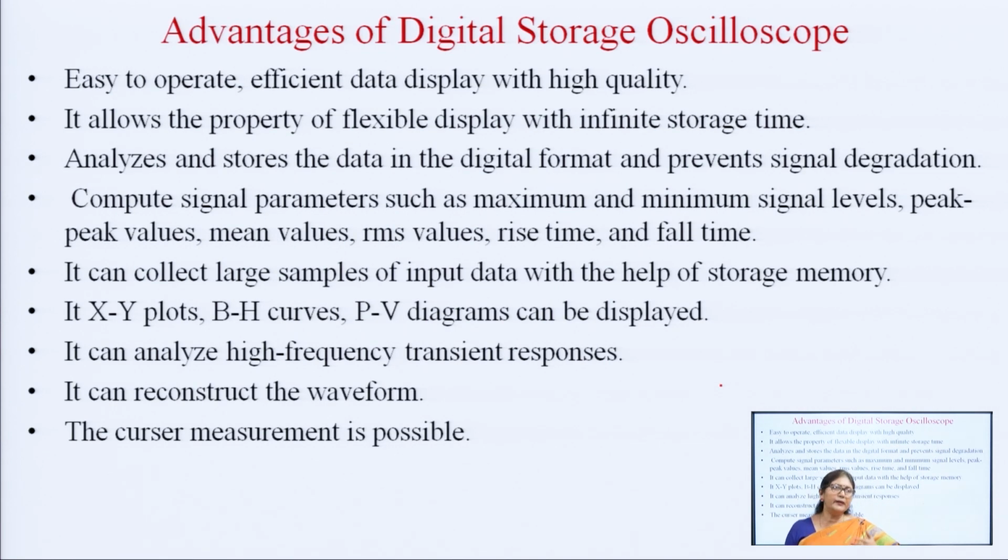As for the advantages, we can display the XY plot on the screen, plot the BH curve and the PV diagram, and it has efficient data display with high quality, and we can reconstruct the waveform. We can measure the signal amplitude at any time by putting the cursor at that point. So, rise time, RMS value, whatever we want to measure, we can measure with the digital storage CRO.